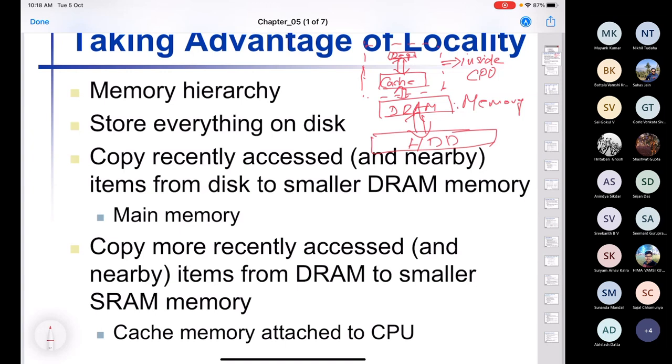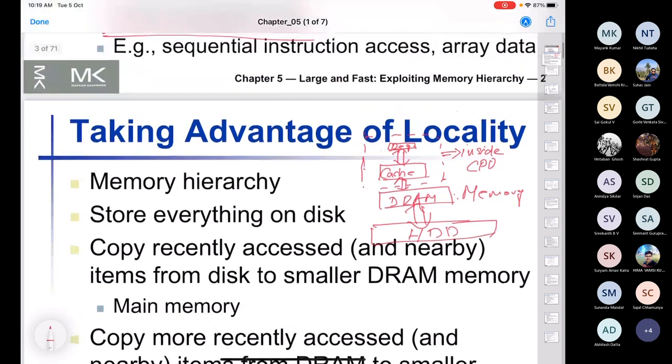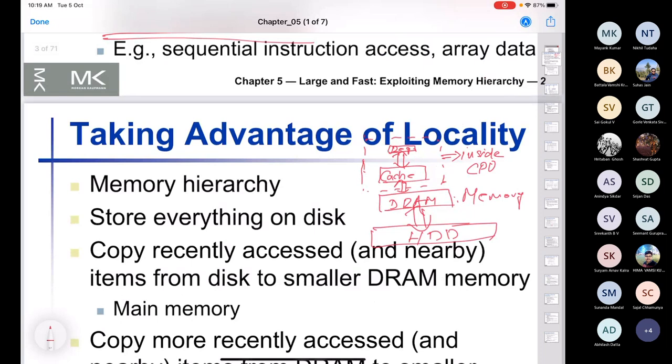The microprocessor interacts primarily with the memory chip, that is your DRAM chip. Because the DRAM chip is much smaller than the hard disk drive, you access certain amounts of program and data from the hard disk drive and put it in the DRAM chip. But access to the DRAM chip from the microprocessor is quite slow. It is affected by something called von Neumann's bottleneck, where 10 to 100 clock cycles might be wasted for the access of this data from memory.